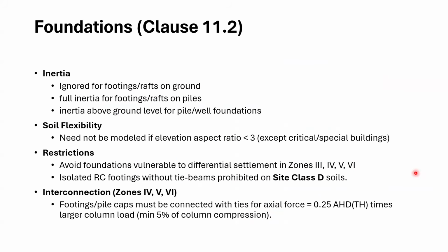Then lastly, we have foundations under the miscellaneous section. When foundations are considered, ignore inertia for footings or rafts on ground, shallow foundations; full inertia for footings, rafts on piles, then inertia above ground level when pile or well foundations. And soil flexibility needs to be modeled in elevation aspect ratio. So guidelines are available, and then there are restrictions.